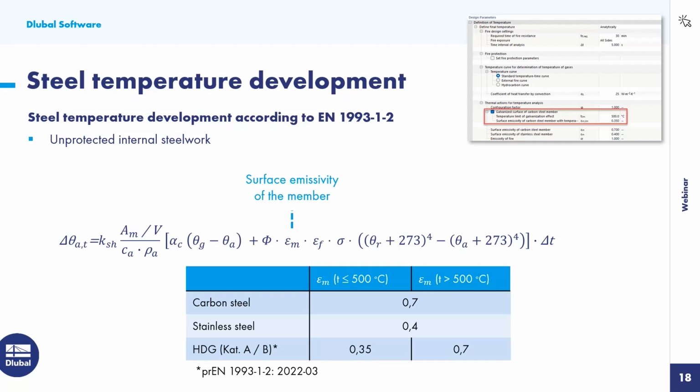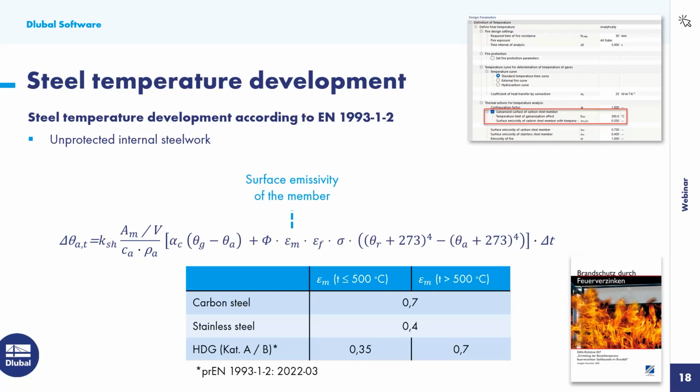If I am correctly informed, this additional regulation has already been included in the draft of the second generation Eurocode. In Germany, this option has already made it into the majority of state building regulations via an additional guideline published by the Institute for Hot Dipped Galvanization, named the DASt Guideline 027.